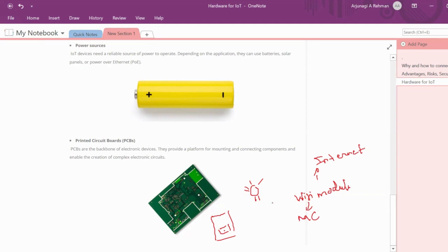Okay, great. Now the signal is coming from your mobile via the internet to the Wi-Fi module and to your microcontroller. But can your microcontroller control your light inside? So let's connect some actuator that can physically turn on or turn off the light. In our case, let's say a relay.